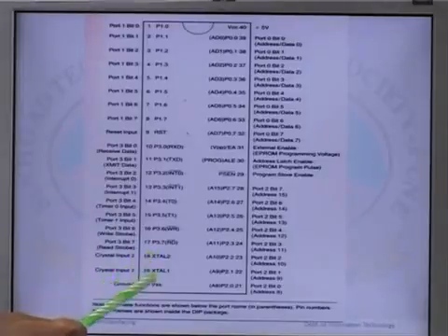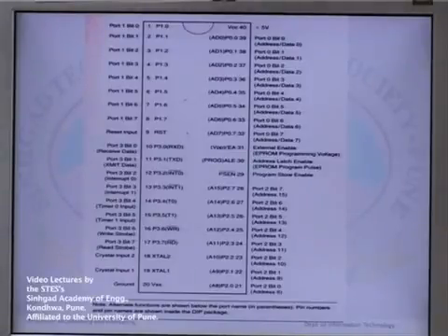Pin number 18 and 19, as shown here, these are crystal 2 and crystal 1. Internal oscillator inputs are nothing but these pins. A quartz crystal which specifies operating frequency is usually connected to these pins. Instead of it, miniature ceramic resonators can also be used for frequency stability.